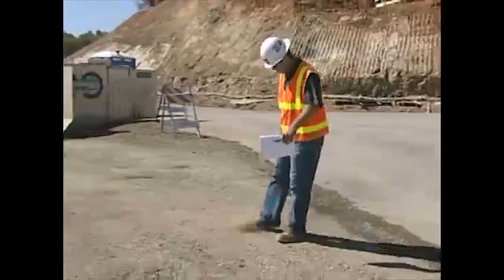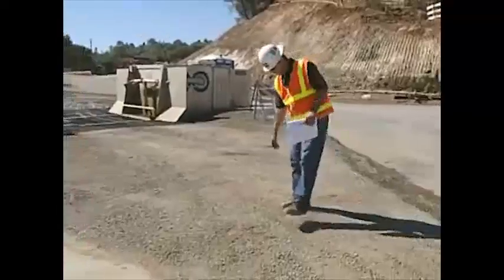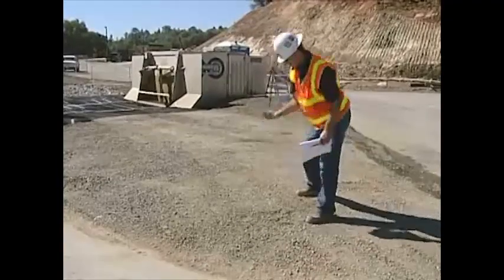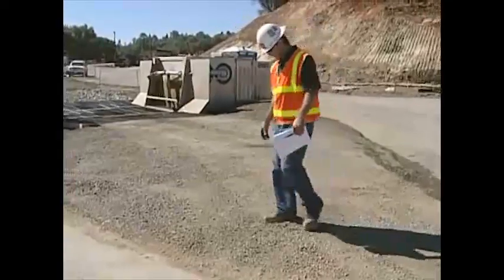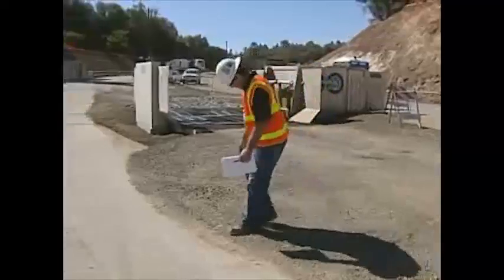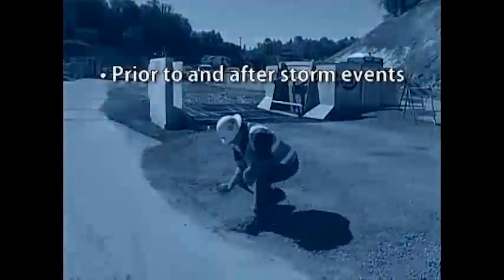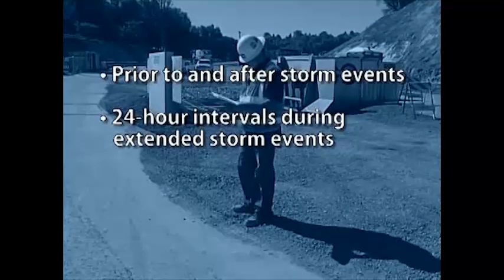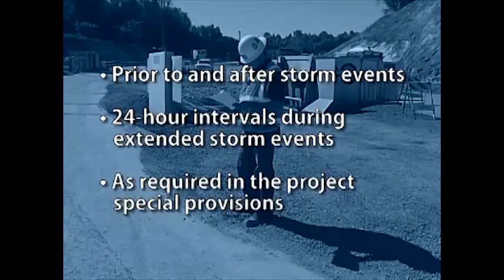Inspections are also required during dry weather to ensure proper implementation of BMPs, such as a tire wash, which is not necessarily weather-related. During the rainy season, inspections must be completed by the contractor prior to and after storm events, at 24-hour intervals during extended storm events, or as required in the project special provisions. The project special provisions also require copies of the inspection checklist to be submitted to the resident engineer within 24 hours.